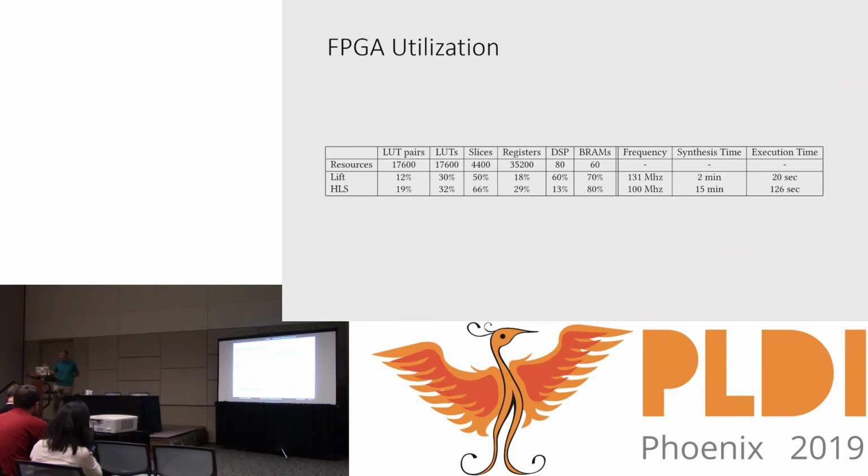So the one thing to notice is the hardware acceleration on the FPGA, which can perform multiplication operations and additions much faster than if you were to synthesize those algorithm units in the FPGA fabric.